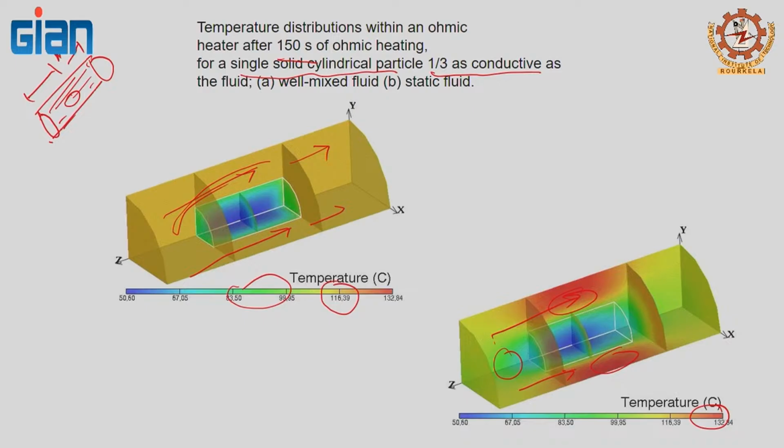So, in other words, you have to understand how well the electrical conductivity in the liquid and solid are matched, so that for the current it looks like the same mass, whether it is a liquid or solid. If it is the same electrical conductivity, it is going to heat much more uniformly, whereas when the values are different, then they are going to have different temperature distributions.